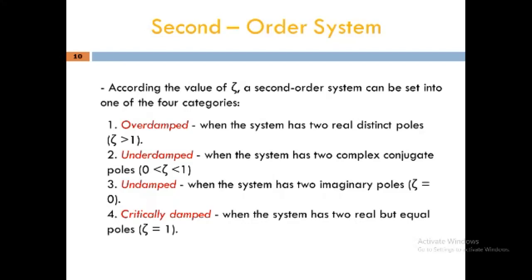Thus, in our present study, we will apply some known methods of steady state analysis, which will allow us to simplify the classical approach to the transient system. Let us therefore begin the study of transient analysis by considering the simple series RC circuit. After switching, we will get a source-free circuit. Basically, the switching operation is done between the R and C circuit and a source-free circuit, in which the capacitor C will discharge via the resistance R.